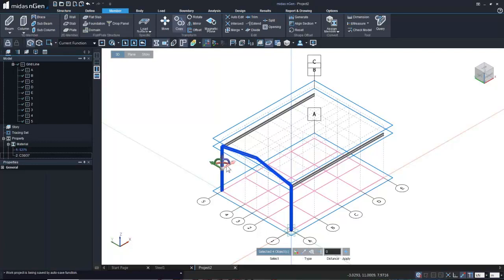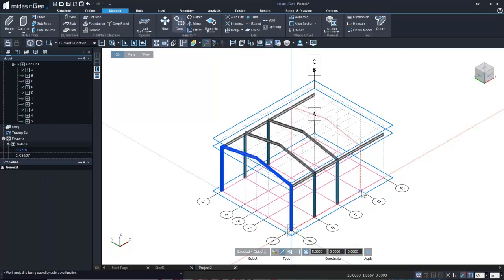There is one option where you can drag and put it at any location as you desire. Or you can use this snapping tool, selecting 2 points: you click on one point, then click on the other point and specify the distances. That's what I'm using right over here, using select by 2 points, and there we go, we're done with our main frame.